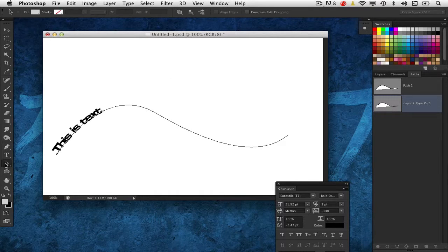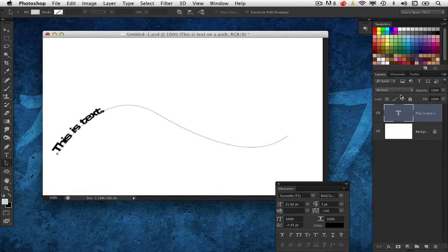That's because this control point here stops right on the edge of that graphic. So I'm going to grab it and extend it out here so I have plenty of room to reposition that. I can position it just by grabbing this middle control handle and positioning it where I want on the path. And then I can set my in and out points of where I want the text to stop or not stop on the path. And you can, again, drag it to the top and bottom of that baseline just by clicking and dragging top or bottom, just like that. So it gives you the flexibility of not just adding text and formatting it inside Photoshop, but also applying it to a path and then having control over it when you do that.